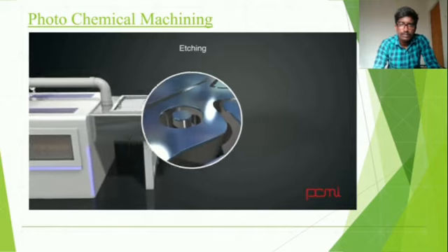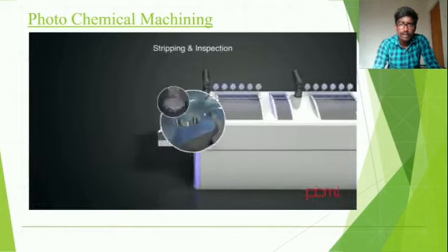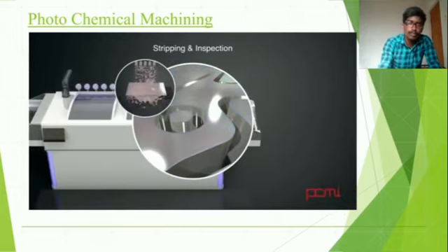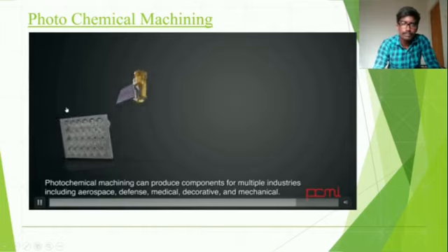When the sheet is finished etching, the remaining resist must be removed. This is done by applying resist stripper, in which the stripping process dissolves the resist. The excessive photoresist coating is removed, and the result is the finished etched part.